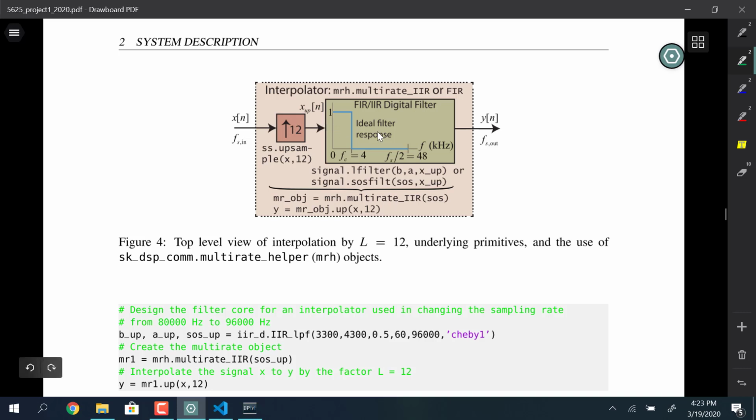And what you're doing is you're jumping the sampling rate up through that 0 insertion mechanism, but then you end up getting images in the spectrum, and really what you're having to do is interpolate samples where all those zeros are, and you would do the interpolation with a low-pass filter.